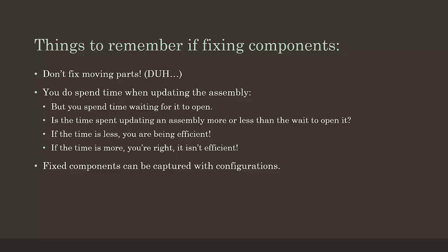Kind of make sense? All right, and be careful of the logic loops, especially here, because I have hundreds of components all intermingled with each other. I think one of the things that I'm running into with the long load times is that I'm getting this error, and you guys have seen it as well. You're working on assembly, you do that one wrong mate, you wanted it concentric, made it tangent, and then you get to sit there and SolidWorks punishes you while it's sitting there, and you're like, come on, I know I did it wrong, let me fix it. Be careful of these. These will come and bite you here because you don't see them right away. So keep that in mind with those cyclic redundancies.